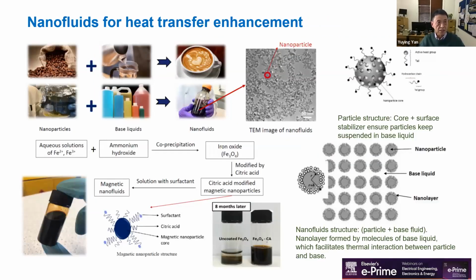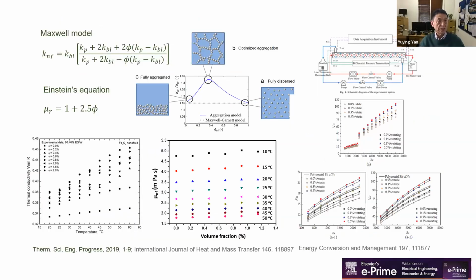Nanofluids are suspensions of nanoparticles in a base fluid and can be easily prepared nowadays. And we just mentioned that, although there are issues in terms of application in flow boiling, no phase change applications to electronic cooling or thermal management are still attractive. Some progress has been made over the past few years. You can see our publications and also the applications of a nano-encapsulated phase change material to heat transfer and to energy storage, and possibly for pulsating heat pipes could be very attractive.